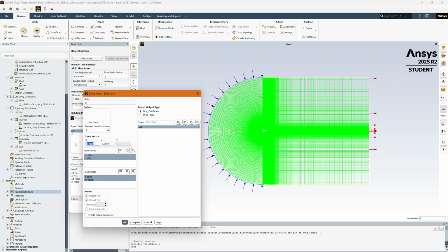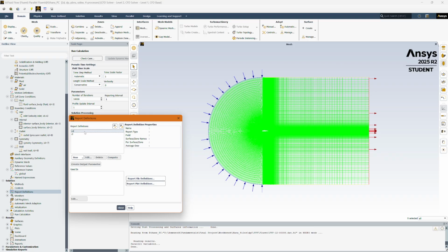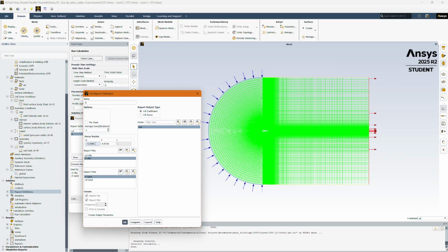Before we run our initialization, I'm going to quickly switch this over to 1 and 0 to mimic the actual direction of the drag coefficient for a 0-degree angle. Those are set to a 21-degree angle of attack from the last time when I ran this. So let's make sure to change this one as well. So this goes to 0, and this goes to 1.